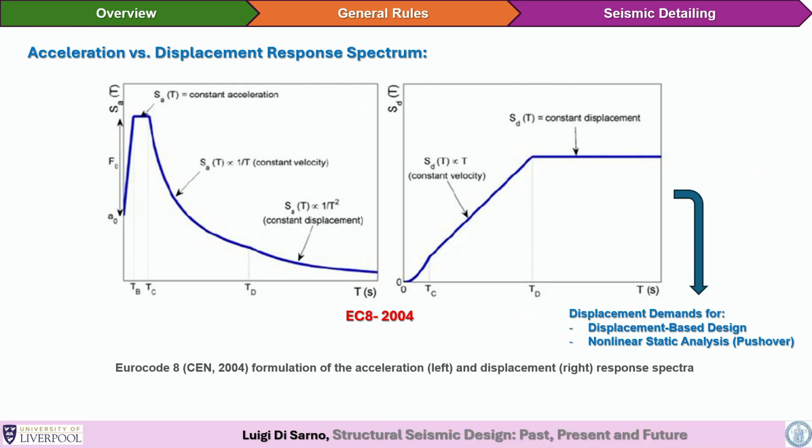And of course, there are also different methodologies being adopted. Since 2000, since the millennium, there has been a methodology particularly adopted in Europe through the work of Nigel Priestley and Michele Calvi on displacement-based design. So typically, in seismic design, we look at the forces as the primary design parameter. Here we are looking at the response of the structure. The structure does not really know forces. Forces are a sort of invention. It's based on an idea that came from Cauchy, in the 1880s.